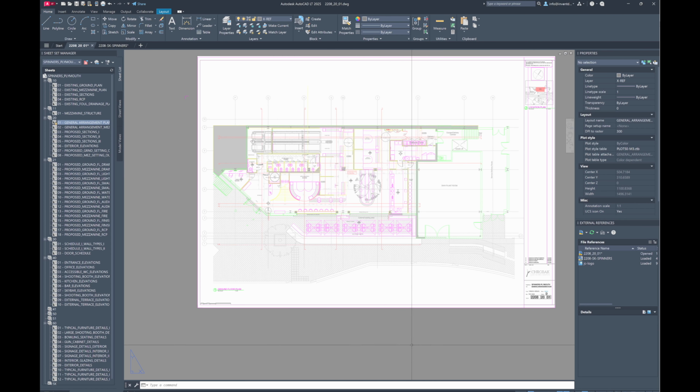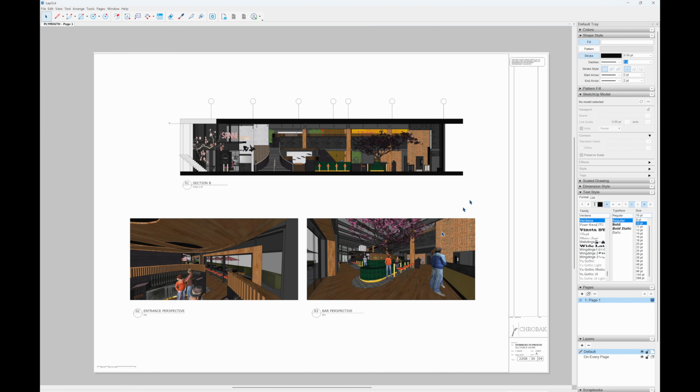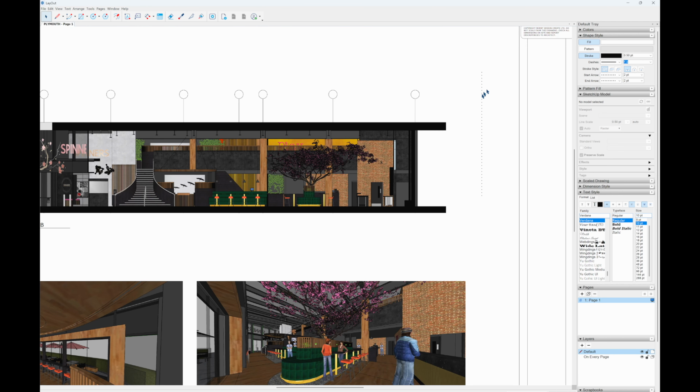In a way, you can. So, if I drew a line, let's go to layout. If I drew a line here in layout, I can manipulate this line. So, for example, I do a line, I select that line, and then I can come here under shape style and just go, well, I want to create that as a thicker line. So I can create this line and manipulate it, but not to the extent that I can in AutoCAD.